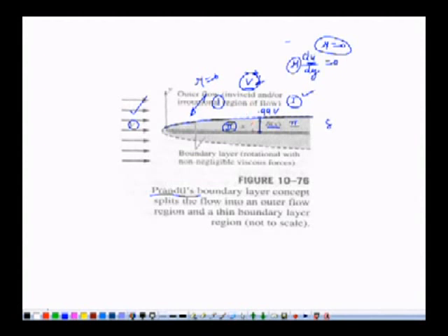And inside the boundary layer, we apply the NS equation for two directions, meaning x and y direction, and it can be solved. Right. Now in modern days, there is no need to have this boundary layer approach. These can be solved with the help of software like Fluent, in which we need to give just boundary conditions. We need not assume the boundary layer, right. But to understand the concept and its importance, it is very important to still know about the boundary layer. Then only we can understand several phenomena with the help of boundary layer, and we can solve the problem.